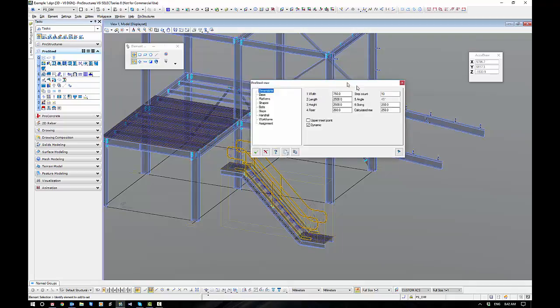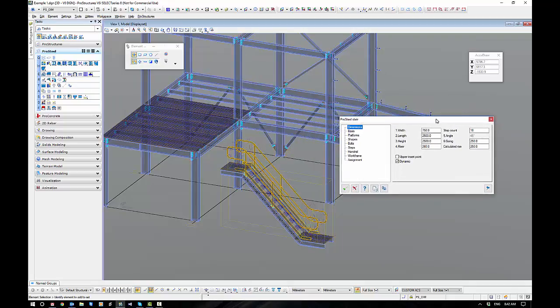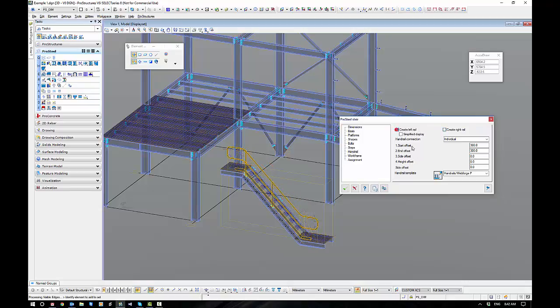So I'm just going to tidy this up a little bit. You can see the handrails and stuff are on, so I just want to turn these handrails off. Come to the handrail and I'll turn this guy off, and the left and right off. It just makes it easier and quicker for everything to update while it's processing all the stairs.